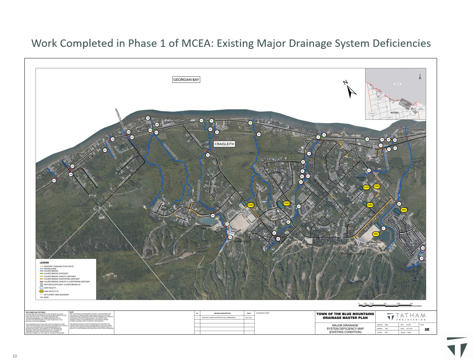The depth and velocity has been assessed to determine if the crossing is passable by vehicular traffic during the regulatory storm. The MCEA's safe access and egress criteria, specifically a depth of ponding of less than 300 millimeters, a velocity less than 1.7 meters per second, or a depth-velocity product less than 0.4 meters squared per second, has been used to assess whether a crossing is passable. The same criteria have been applied to major overland flow routes.